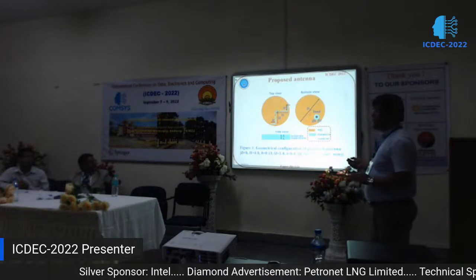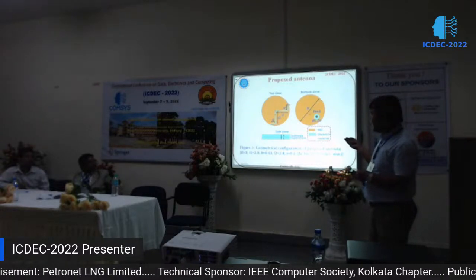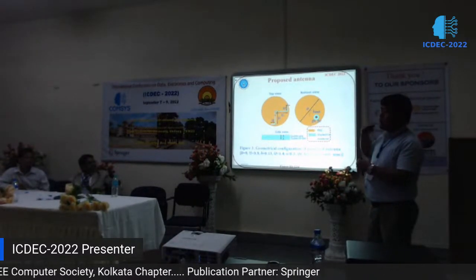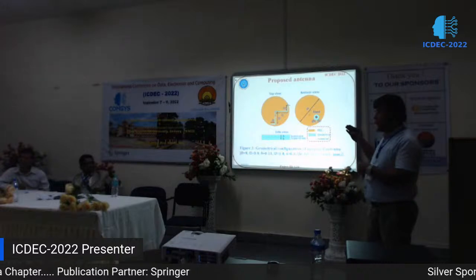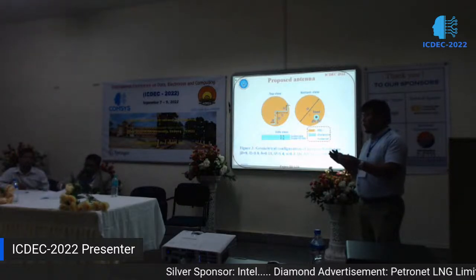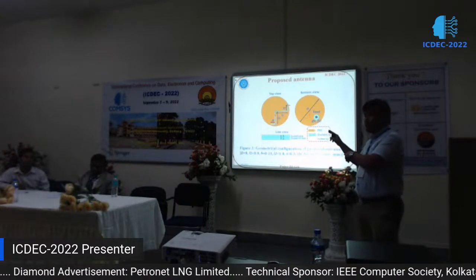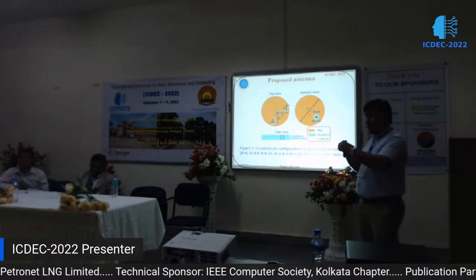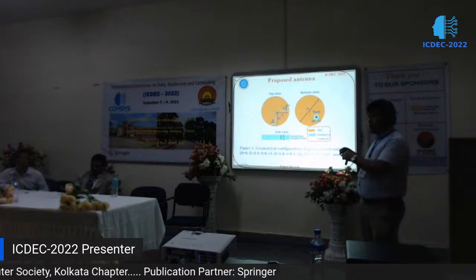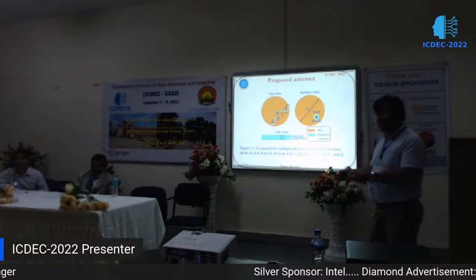Sorry for that. For this design structure, if we consider the governing equations of the microstrip antenna, with a diameter of 9 mm, it will give around 15 to 16 gigahertz. But at that time, what I considered is the dielectric property which we are supposed to load in that environment. I took this for 2.45 gigahertz, that is 38 permittivity and 0.6 Siemens per meter. If I give that effective wavelength, then it comes to around 9.002, something like that. So based on that, I designed this. But sir, whatever you are suggesting, I will work on that and try to improve it.